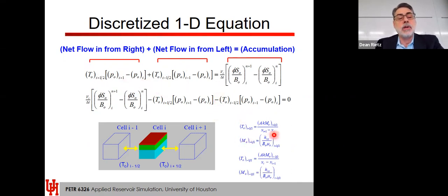So I guess we can go here. If you look at this, this is the transmissibility equation. It's the part of Darcy's law that has our area, our permeability, and then M is our mobility term, and then X minus X1. So we're looking at the distance between those, because remember, Darcy's law has a distance component in there, right? So there's a length component. That's what that is. So M is the mobility.